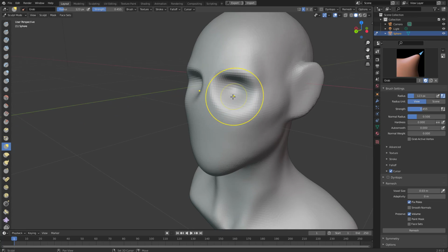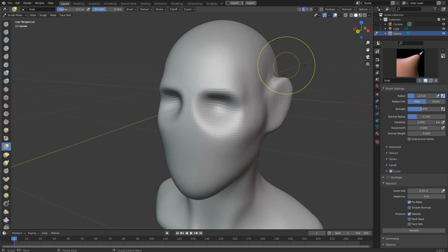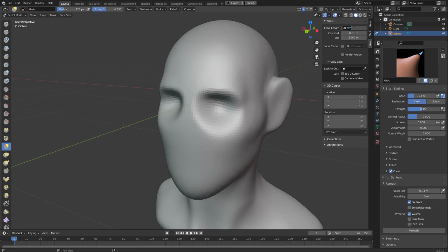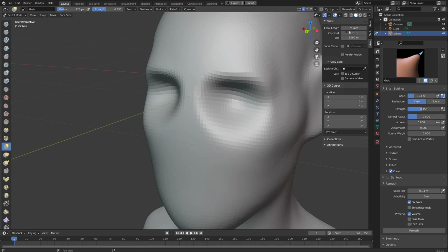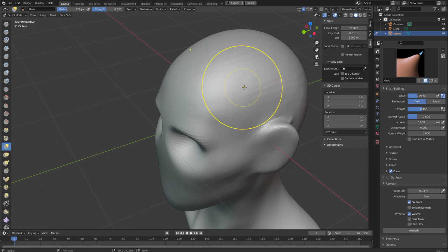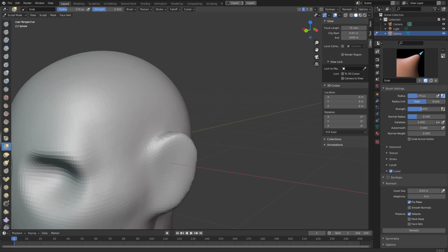Oh, and one more thing worth mentioning is the distortion you're seeing. That's very common in 3D software, that they make too much of a distortion here. You hit the N button to pull up the settings, go to View and change the focal length to 75. That oftentimes is going to reduce the lens distortion of the camera. So very, very useful.